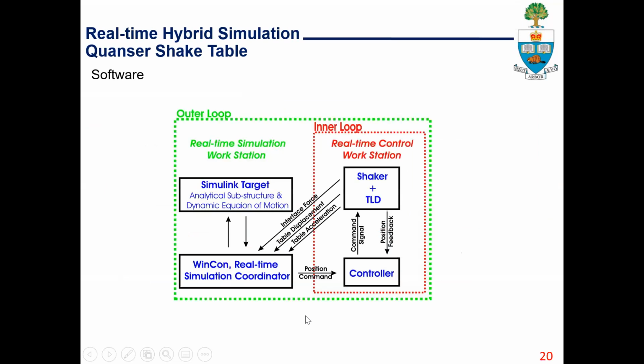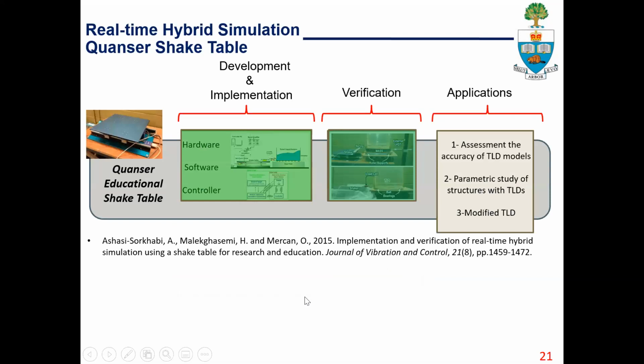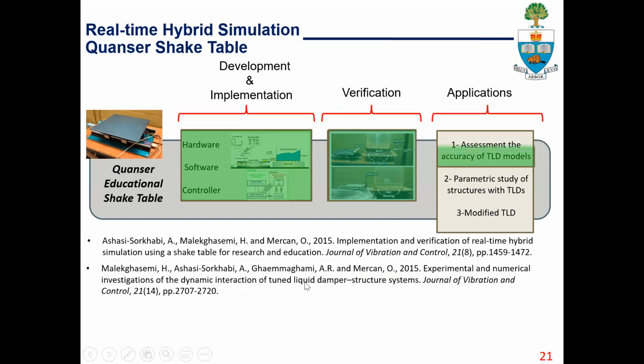On the software side, the inner loop was already there. The Quanser shake table comes with its own controller. What we needed to do was to introduce the outer loop with the integration algorithm. And we use Rincon real-time simulation coordinator to synchronize the two. And we published the development, implementation, and verification of this platform in 2015.